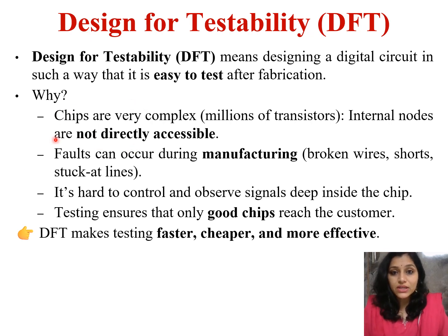But why is it required? Why is DFT, design for testability, required? Because chips are very complex. You know that millions of transistors are present in a single tiny chip, and internal nodes are not directly accessible for testing. If I have millions of transistors in a chip, I can only test primary transistors directly, by applying external inputs to the primary transistors at the input side.